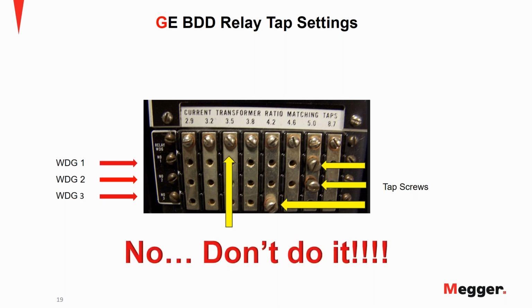And the other one is this guy. Don't use this as a tap. It doesn't work. I've seen relays that I went back and did testing on, where this screw right here is to hold the tap bar in place, and I've seen this being used as an actual tap. And that is not correct. These are thumb screws, and they have a little bit bigger head on them so that you can put them in there with your fingers and hand tighten them.